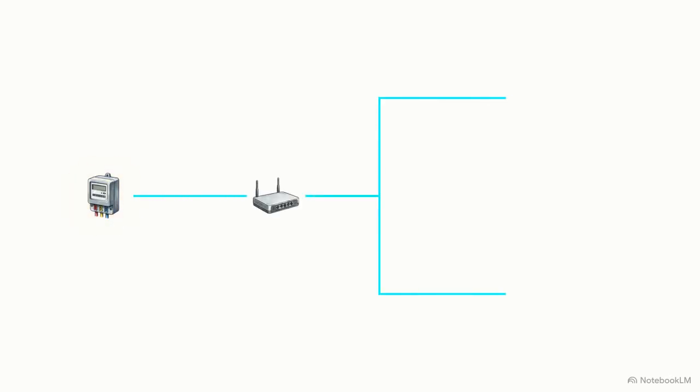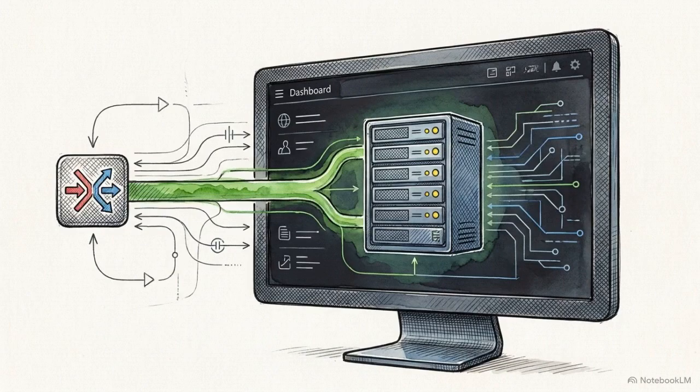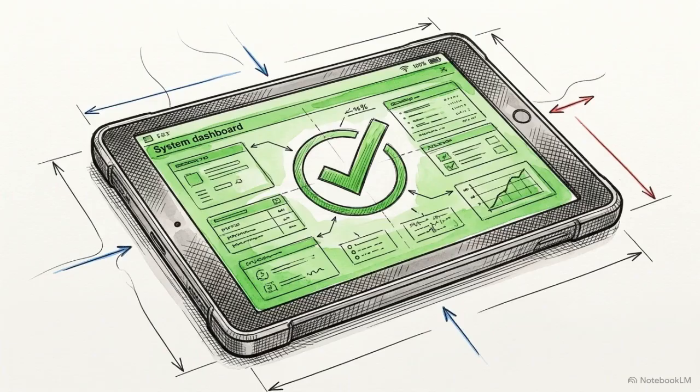The testing protocol extends beyond the physical meter face. You must also validate the network transmission reaching the substation automation system and the energy control center. The connection back to the local gateway must remain clear, showing exactly 0 unresolved alarms on the control center interface.